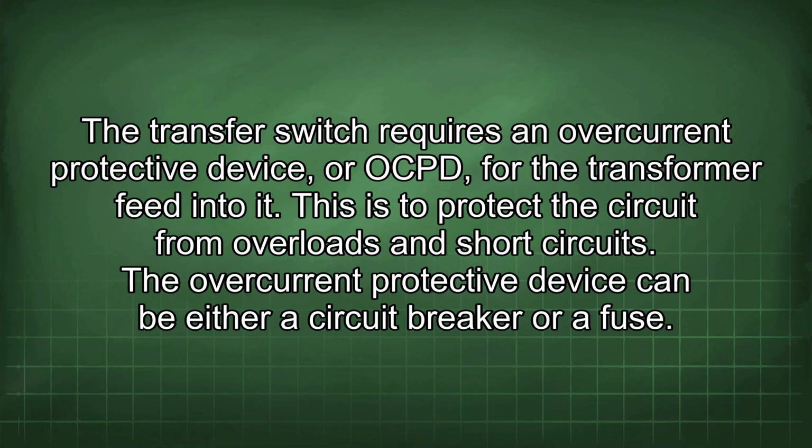The transfer switch requires an overcurrent protective device, or OCPD, for the transformer feed into it. This is to protect the circuit from overloads and short circuits. The overcurrent protective device can be either a circuit breaker or a fuse.